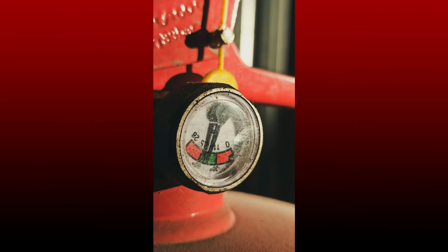Visual inspection should be every 30 days and will include inspection of physical damage, working components, gauge pressure or weight, documentation or electrical monitoring, fire extinguisher operation and use.